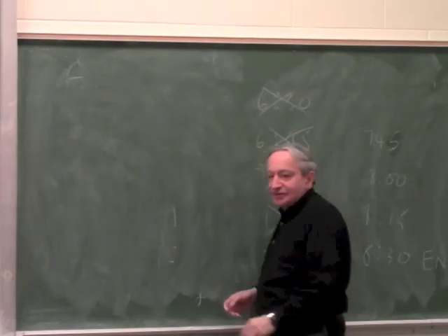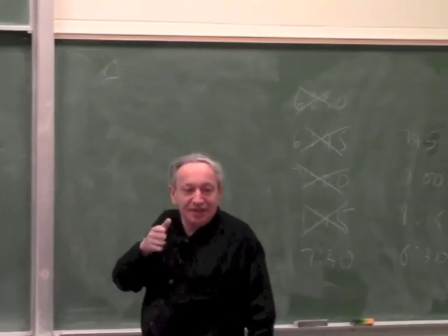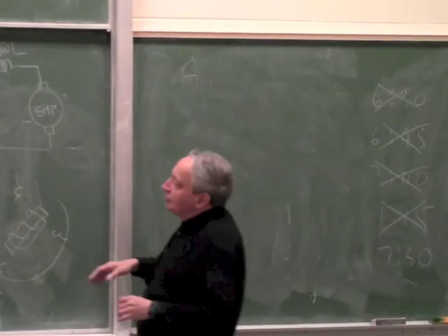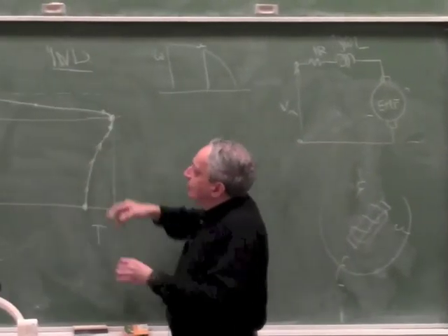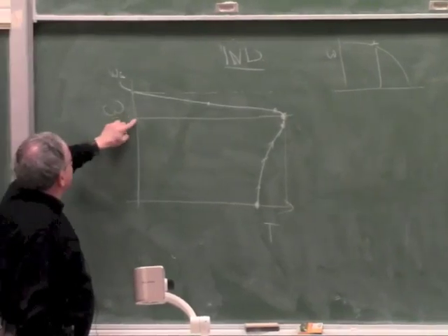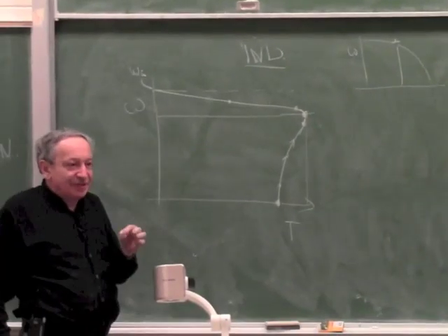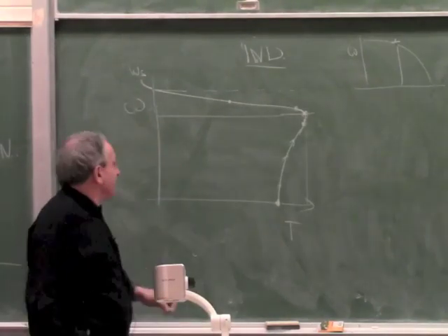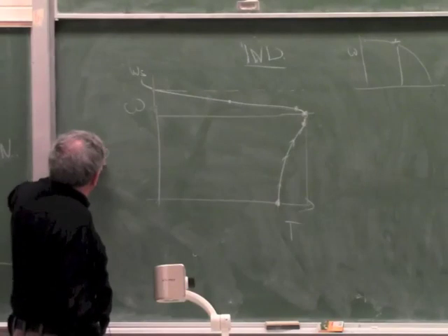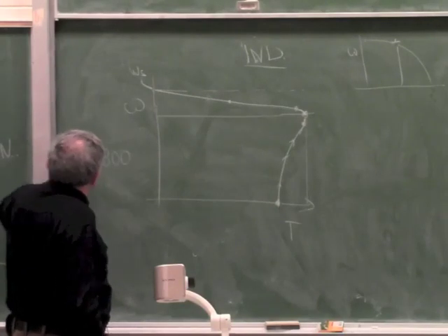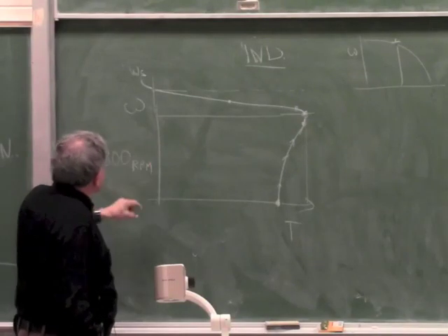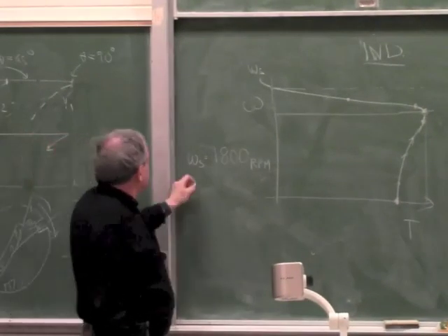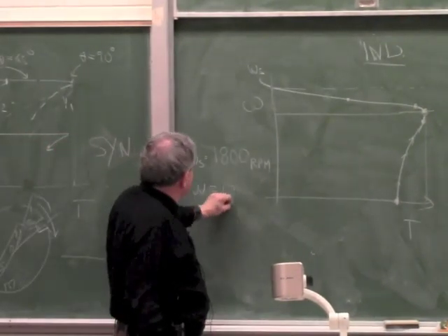Of course, there are other factors like the type of laminations, because again, there's hysteresis losses. There's many other factors. So altogether, it's optimized to work near omega S, and I gave you an example that it works typically 5% below omega S. So this point is typically 5%. If you want a better number, the typical motor in your home is 1800, omega S is 1800 RPM. I'm just writing it in RPM, not in radians per second, because that's what the motor nameplate says. And the actual omega this motor works at is 1725.